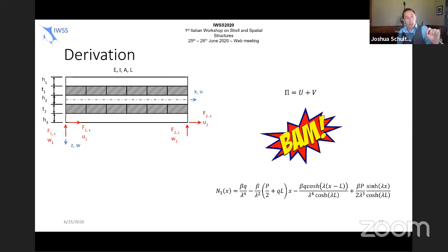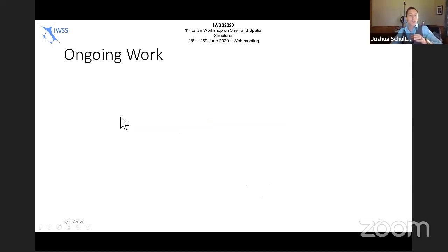And then what's valuable for the designer is we can take those displacements, convert those into our stresses, and now I can give the designer a closed form solution for the stresses at each one of the inner layers of these plies. So what we've done right now is we've taken that and we've accomplished that for a simply supported and for a fixed system.